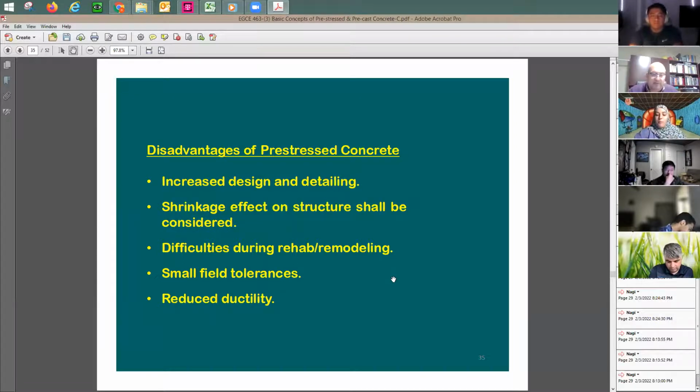Member design is complete. In here, the surface stresses, and then you're going to have phases. You're going to have during construction, which means during the cast, at the time of transfer, and then after you apply dead load, after you apply all the service loads, you're going to have more than one stage at which you need to calculate the stresses and be sure that you're not exceeding the limits, whether it's going to be in tension or compression.